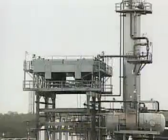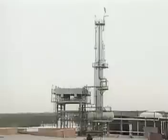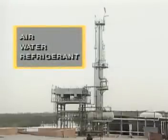The condenser is used to convert the vapors produced during distillation into a liquid. It does this by lowering the temperature of the vapors. One way that a condenser in an overhead system can be classified is by the type of cooling medium it uses to cool vapors from distillation towers. Among the media most commonly used are air, water, and refrigerant.